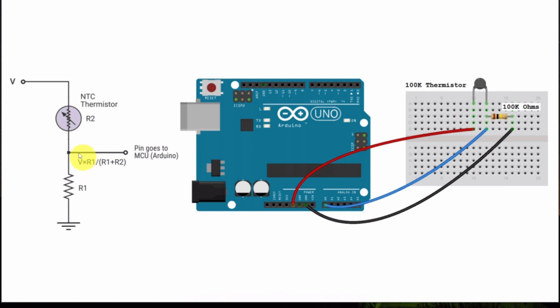So over here is our thermistor, and we're going to use a pull-down resistor. So this forms a potential divider from 5 volts down to 0 volts and provides a voltage which is connected to the analog input of our Arduino. So here's what the actual breadboard would look like. So that's the hardware involved. There's your pull-up, there's your thermistor as per that drawing.